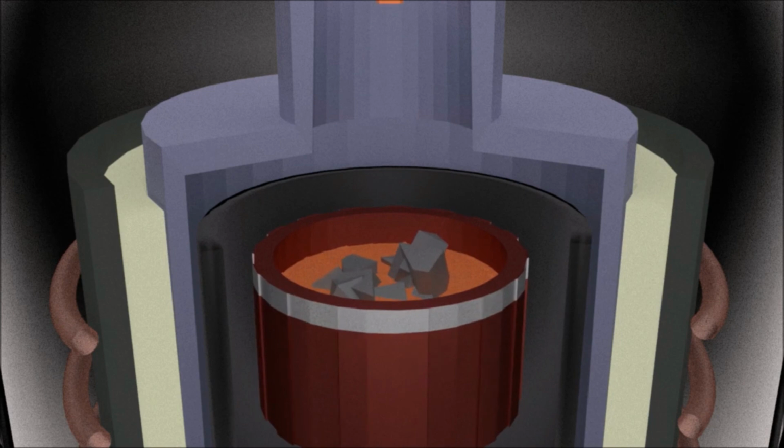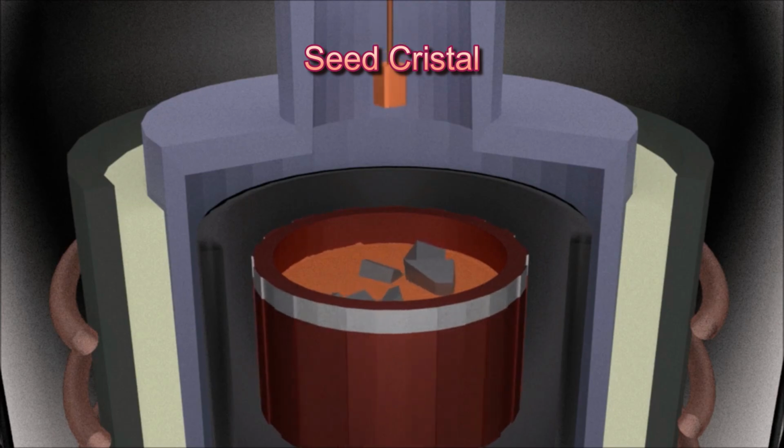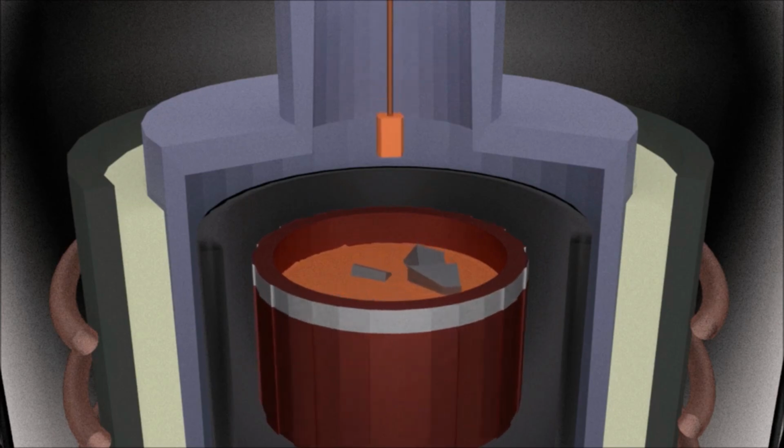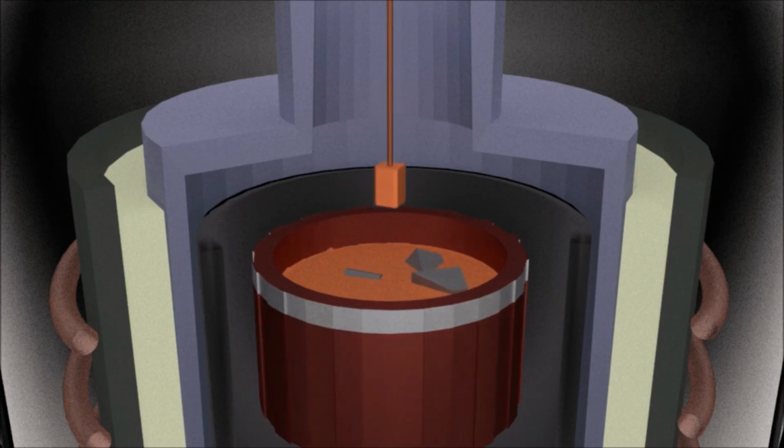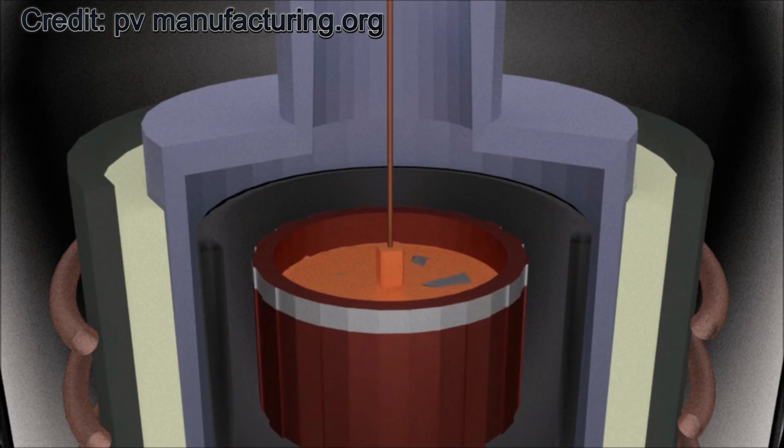A very small crystal called a seed crystal is slowly lowered into the molten silicon. This seed crystal already possesses a perfectly ordered atomic arrangement. As it touches the molten silicon, atoms from the liquid begin attaching themselves to the seed crystal structure.